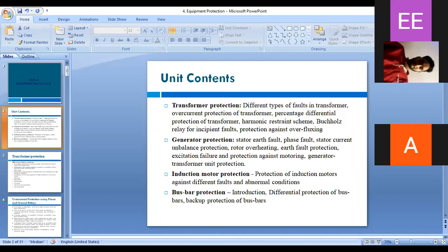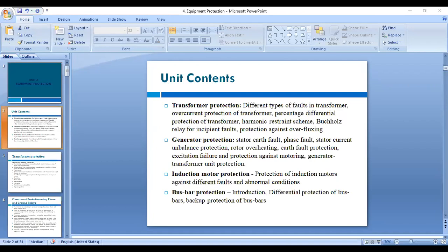Okay, so when this operating coil current increases, what will happen? It will attract that arm so that the contacts of the relay get closed. Actually, the relay contacts are open, and after the occurrence of a fault, these contacts get closed. So when the difference of current is flowing through that relay coil, only then is this relay operating. That's why it is called differential protection.